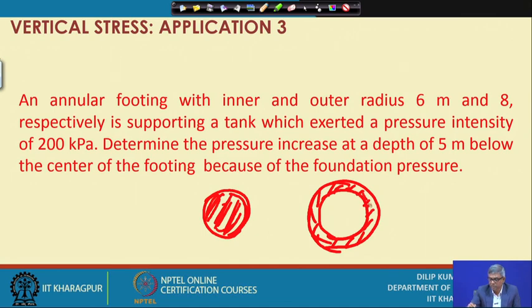So, if these portions are loaded, then what will be the pressure at this point? There will be pressure below this of course, but what we are interested in is the pressure at the center of the footing and at a particular depth, that is the depth given here, 5 meter. So, to find this out, let me see the calculation procedure.